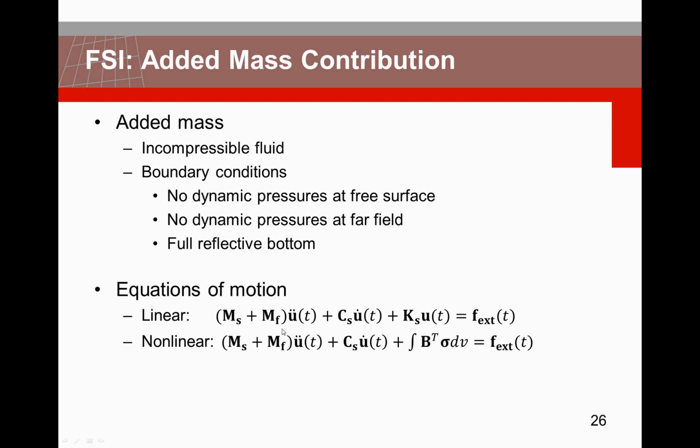So you must make sure, of course, that the fluid part that you model is large enough to take into account all the fluid that is in movement. What you see often is, for instance, that the length of the reservoir at the dam is 5 to 10 times the height of the dam itself, to make sure that you have enough fluid mass modeled. And what you then will see is you have only added mass, so your mass is now your structural mass plus the added mass from the fluid.